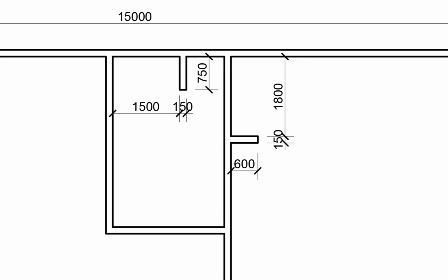Okay, yes, sir, with foundation. But those little walls that are just going to carry their own weight, they won't even go all the way to the roof. You don't need a foundation for those walls. Those walls can be built on top of the floor. And if it's drywall, sir, no foundation at all is needed for that.